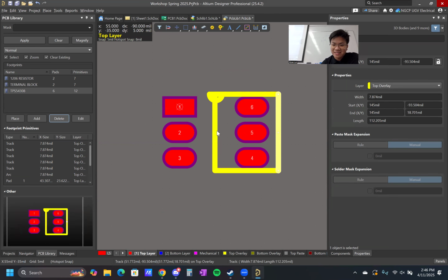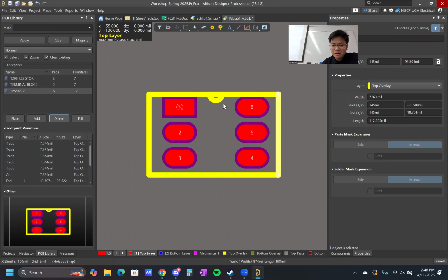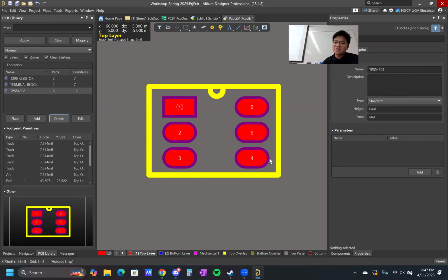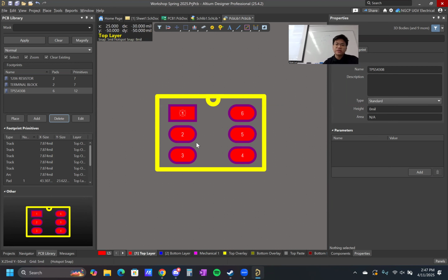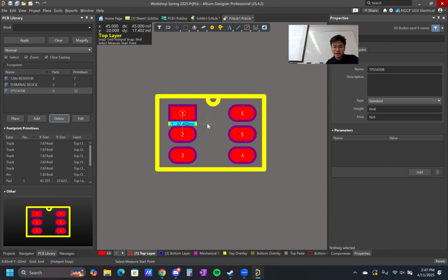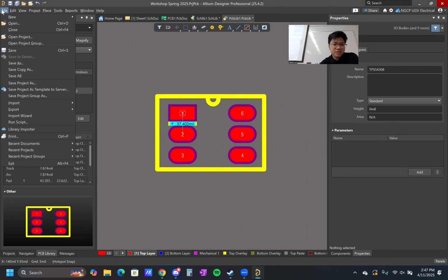We can make our outline look a little better. It is just a really quick and easy way to get the component onto the board. Altium has so many different features, this is just a really quick way to get it. And there's our pad. And if we were dubious about the size, you could go to reports and measure distance to actually measure the distance between the different components. So they give us mils. I think if you hit Z, Shift Z, no. I'm going to change units.